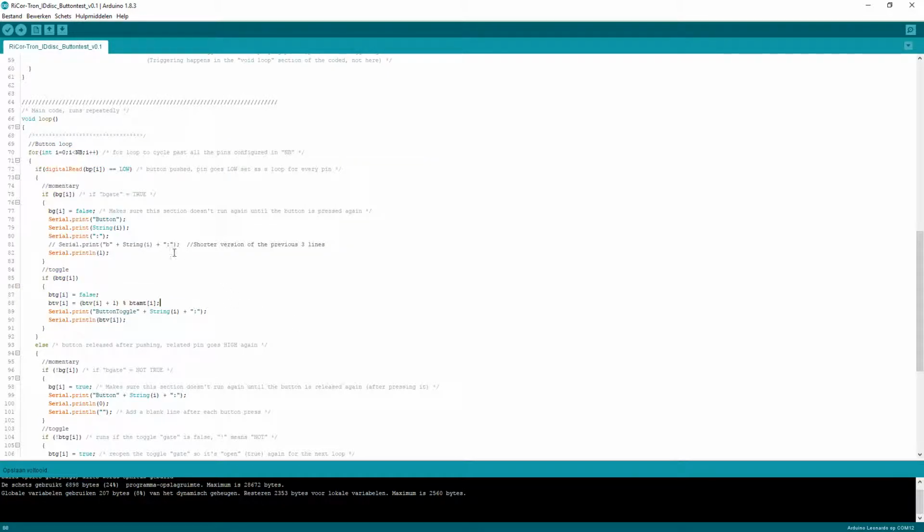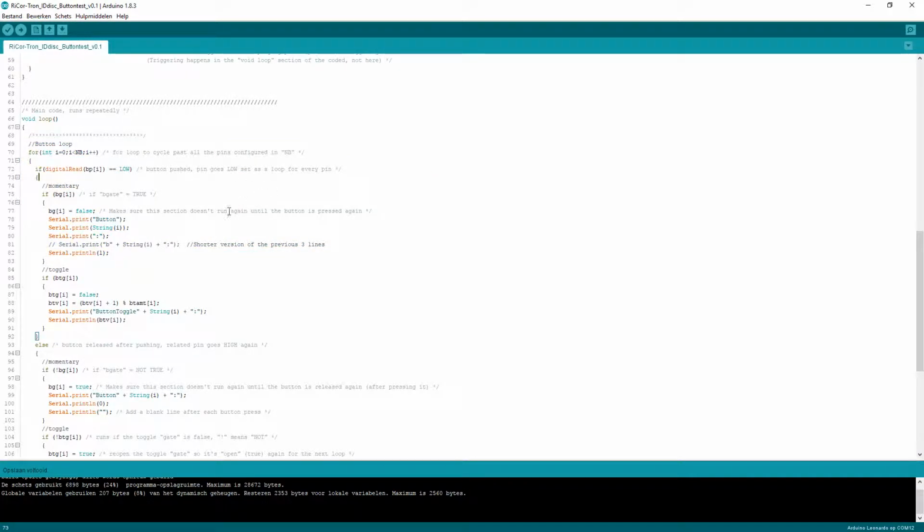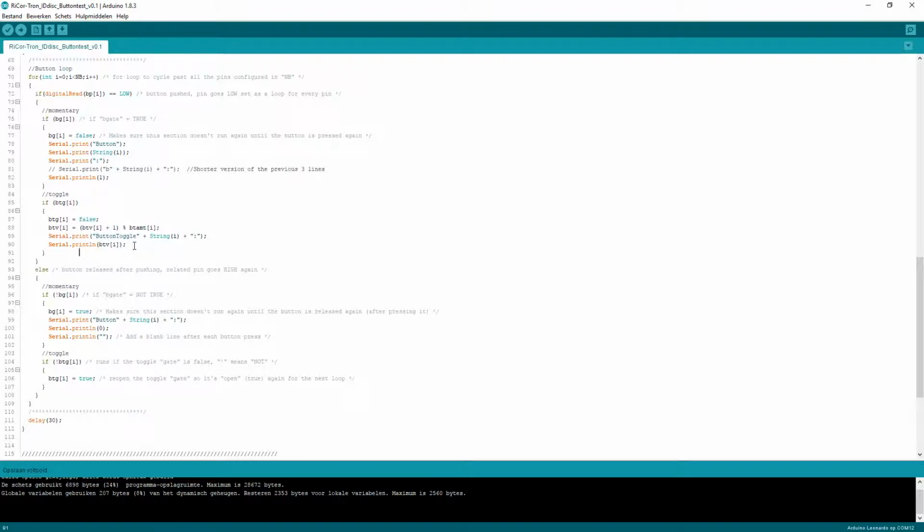So then moving on, you have the button pin. First it goes through and it detects that it's being pressed, and that the pin goes low. Because in this case I'm putting it to ground, so it goes low, and that's mentioned in the output. Then trigger 1 is 1, meaning it's active, it's being pressed. It goes low, but it becomes 1 and it becomes active, just so to say. And every time you press it, it toggles between the amount you set before. In this case, I have just a binary toggle. It toggles between 0 and 1. If I press it, it becomes 1. Press it again, it becomes 0. 1, 0, 1, 0. You'll see that later.